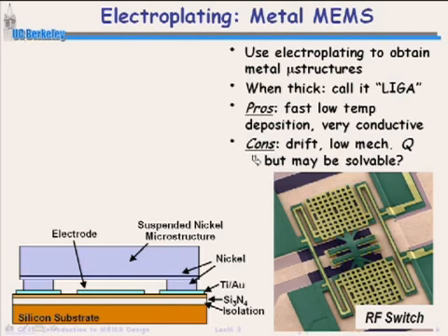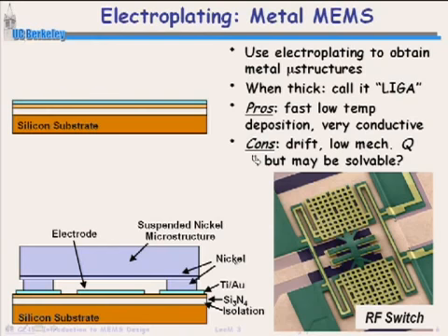that ICs sort of in the end, I don't know which one borrowed from one another, but electroplating is now used quite a bit in ICs to get multi-level metallization. Well, in MEMS, they were doing electroplating quite a bit as well to make structures because it was a good way to make very thick structures. And so for electroplating, same kind of thing. You're depositing some films here. Maybe you'll deposit this film and pattern that. Then you're putting down an aluminum layer. It could have been electroplated or so, but probably was sputter deposited.